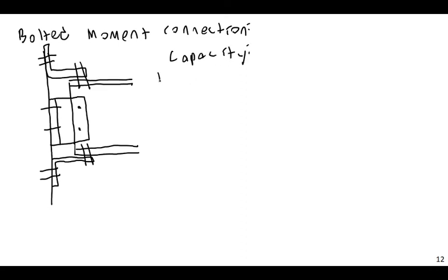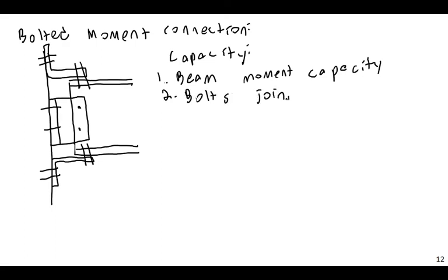The capacity would come down to a few things. One, the beam itself. Two, the bolt strength, bolts joining beam to angles.